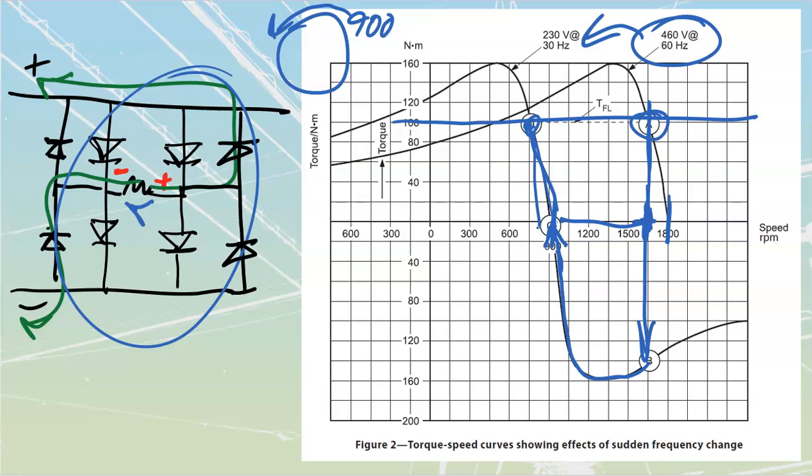This motor, when it slows down like that, if it's going to be a rapid slowdown, we can have a very large amount of current that we are going to regenerate and try to send back in. In some cases, we're going to actually have to divert it. Then we're going to have resistance that's going to be connected across the DC bus that is going to be able to burn some of that off if we're not able to actually put it back in rapidly enough. But most of the time, they're going to be able to take this all back in on the DC bus. There's usually room in either the expanded magnetic fields around the inductor in the case of a CSI, or in the plates of the capacitor in the case of a VSI drive for us to do so.